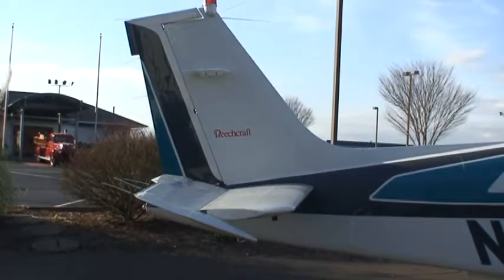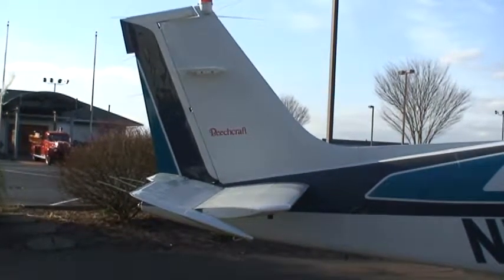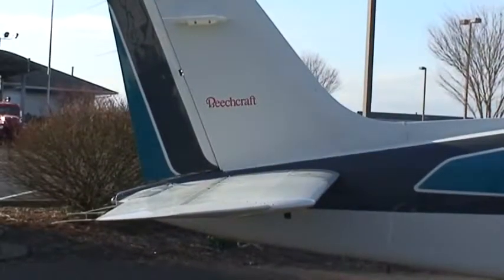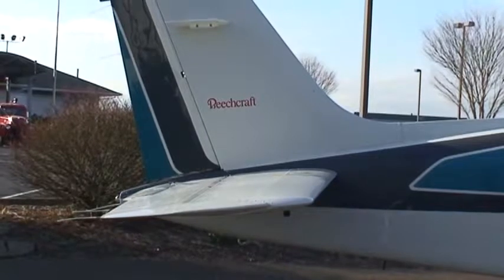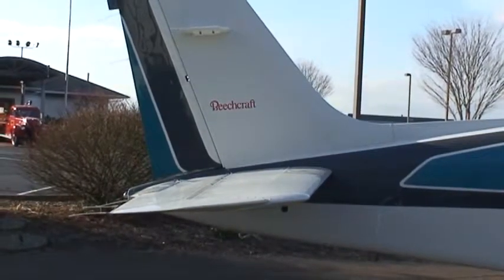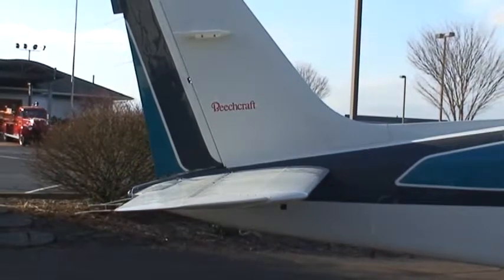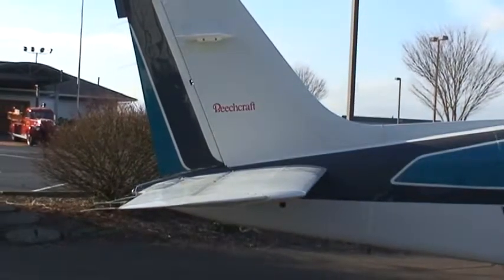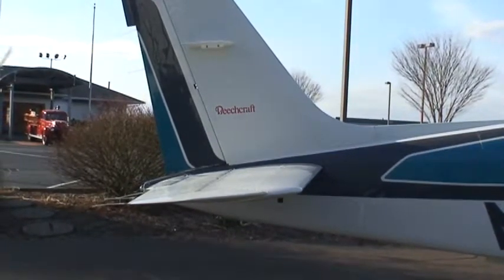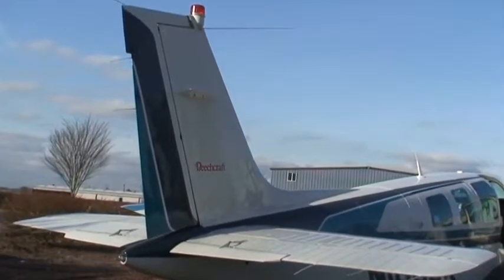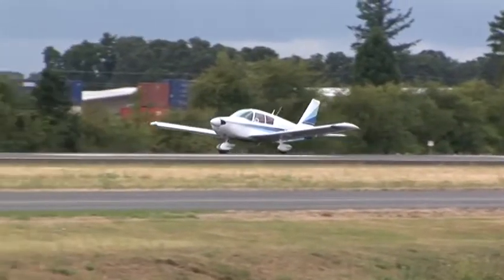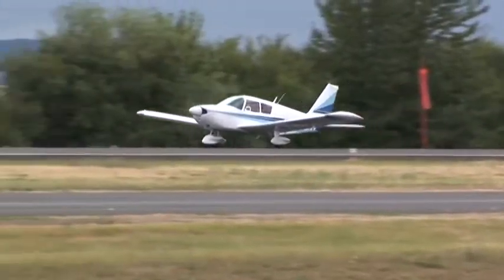The horizontal stabilizer stabilizes the airplane in the pitch axis. We'll cover this in greater detail a little later on. At the rear of the horizontal stabilizer are the elevators you see right here. Elevators are control surfaces affecting movement around the lateral axis. This motion is called pitch and will be discussed in greater detail shortly. Most Cessna and Beech aircraft, like these airplanes, have a separate stabilizer and an elevator attached to it. On some airplanes, like some Pipers, they have a stabilator which combines the stabilizer and the elevator into a one-piece unit.